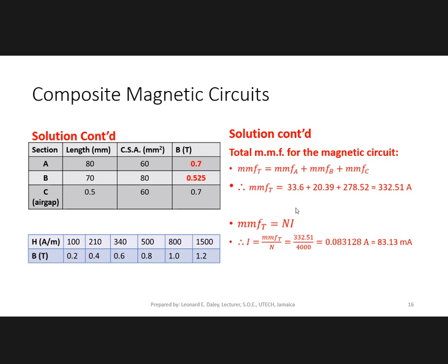Sir, stupid question. Why do we have the air gap again? Well, it's part of the construction of the material. As I was saying, in magnetic circuits, like for example in a transformer, you may have non-magnetic materials inside connecting magnetic materials together, like a wooden screw, for example. So the magnetic material is joined by non-magnetic material, and the non-magnetic material can be considered similar to air. So air gap is really a general term for a non-magnetic part of the circuit.